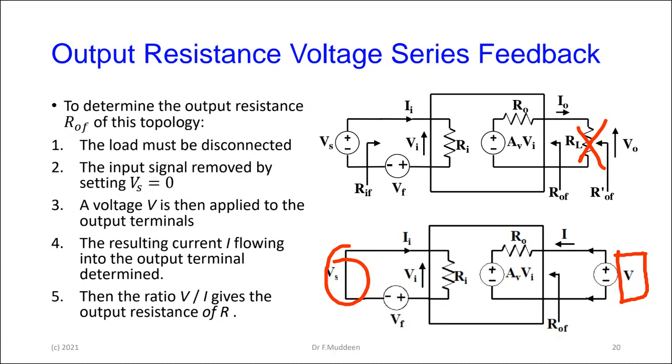Then sometimes, in a practical circuit as well, they do an impedance measurement to see just how high the impedance is on the line coming in. Of course, to do that, you have to disable all the power supplies. You're not going to put a megger or an ohmmeter on a device that is live. You're going to kill yourself.